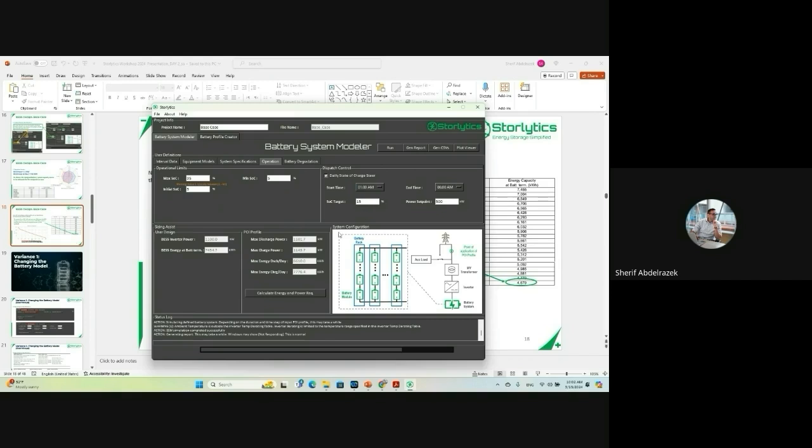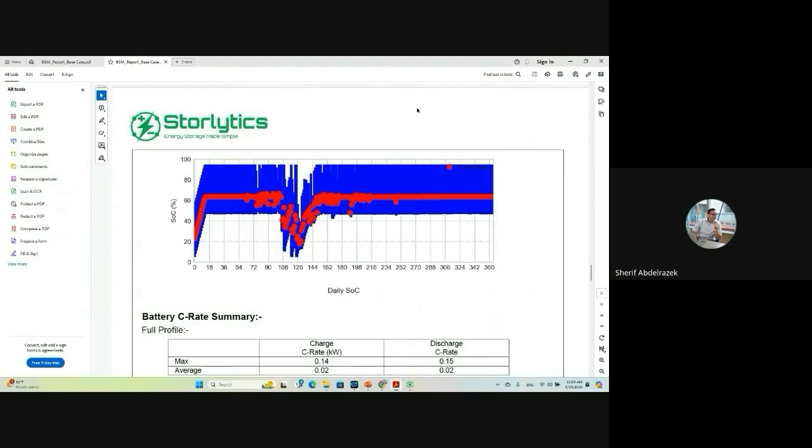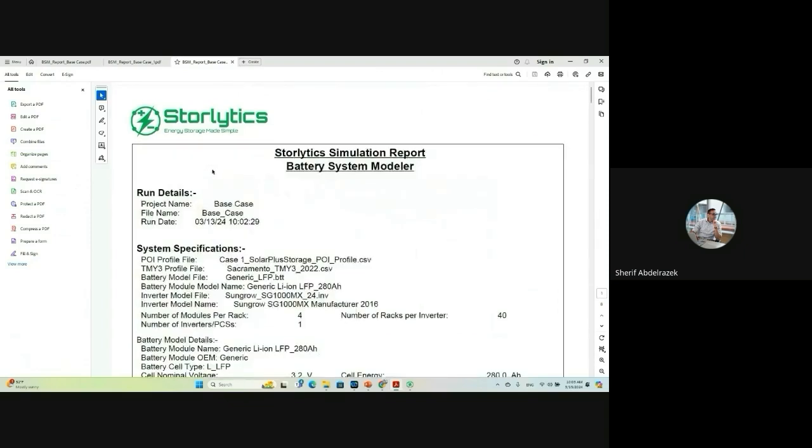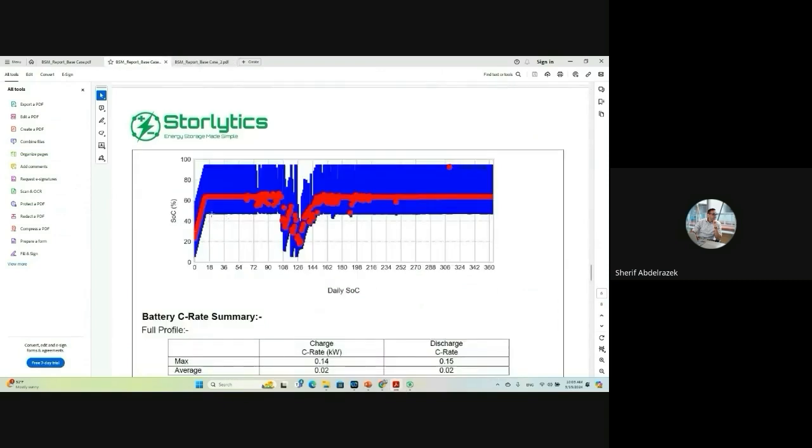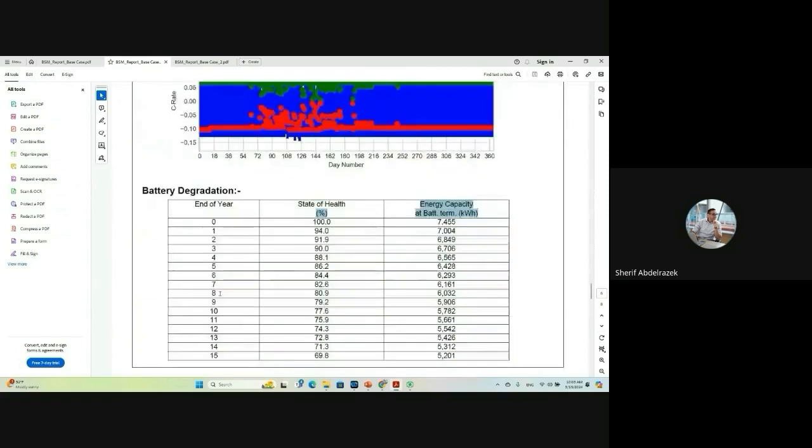So 12 to 6 a.m. works. And the state of charge target, make it 10%, 15%, or whatever you deem appropriate, to be more and more realistic to how the system would actually be dispatched, right? If you were operating a system and you're going to charge, you're probably going to charge first thing in the morning, probably not going to leave the system here. Like, for example, day 18 here, you're probably not going to start at 45%, right? You're probably going to use that time at night to get to a more suitable state of charge.